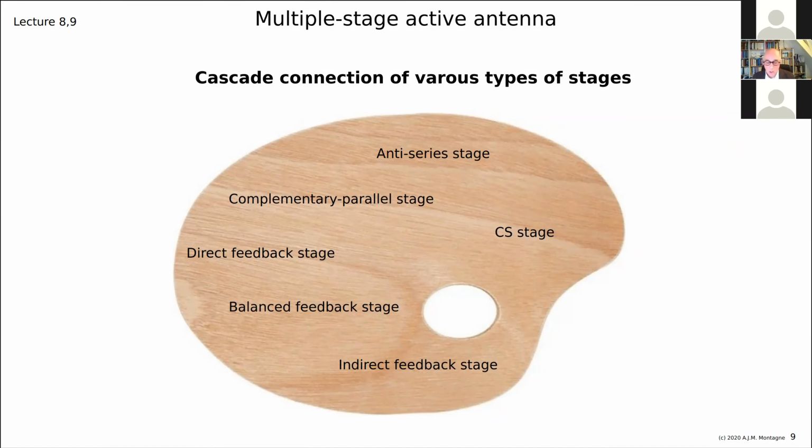And this will be, let's say, one of the bigger assignments for you. You will find out that the single stage solution is not good enough. Well, maybe we can use two stages and we can combine a feedback stage with a CS stage or a balanced stage or whatever. So you can combine stages and see if, combined with cascaded stages, so one stage connected to the output of the other one, you can then make an amplifier that would be good enough.